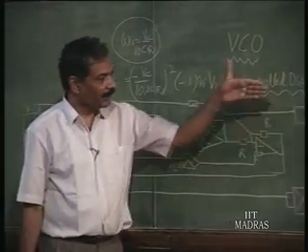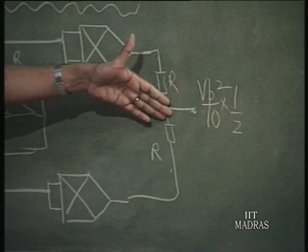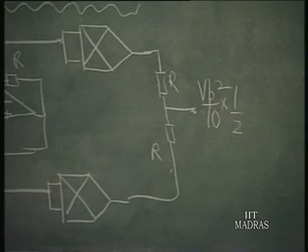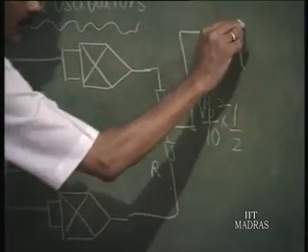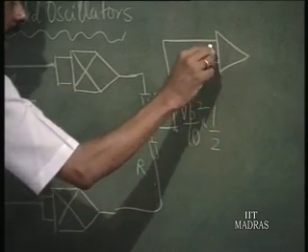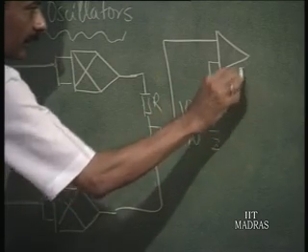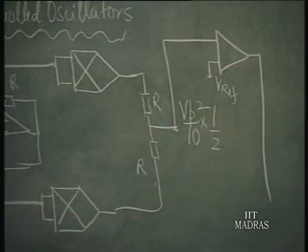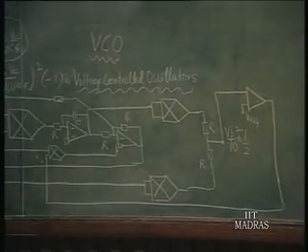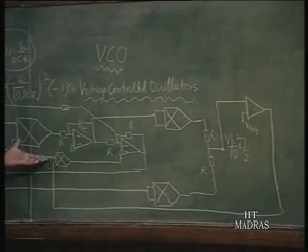So, that can be exploited in getting an amplitude, okay, which is a DC dependent upon the amplitude Vp squared by 20, and this can be therefore compared by means of this comparator, okay, and we can actually put a V reference, and this can be used to control the amplitude. You can see so many multipliers being freely used.